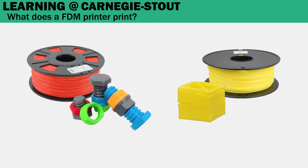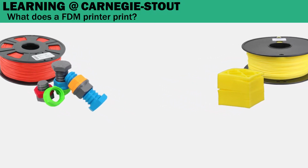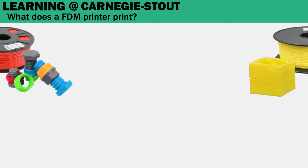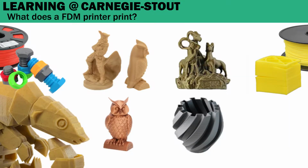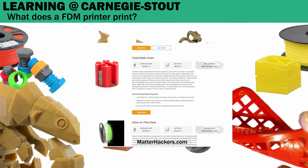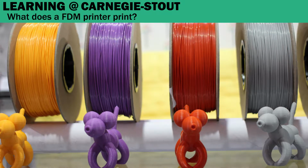Another one, ABS, makes for stronger printed models, but it's much more difficult to print with. You often get warping or layers peeling apart. Also, it releases toxic chemicals when it's printed. We don't use it here for those reasons. You can find different varieties that have different blends mixed with regular PLA filament. Blends of wood, brass, copper, aluminum. There's even plant blends, nylon, and loads more. Again, we stick with PLA here. It's very easy to print with, the models come out looking very nice, and it's really easy to finish with sandpaper, and it paints really well.